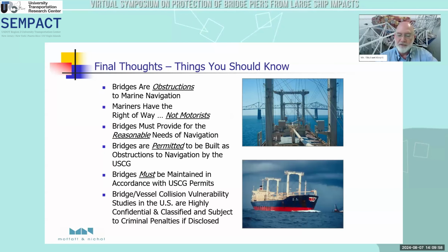So, final thoughts, things that I think you should know as a bridge design community. Bridges are obstructions to marine navigation. Mariners have the right of way, not motorists on our waterways. Bridges must provide for the reasonable needs of navigation, and bridges are permitted to be built as obstructions to navigation by the U.S. Coast Guard in the United States, where we get the name bridge permits.